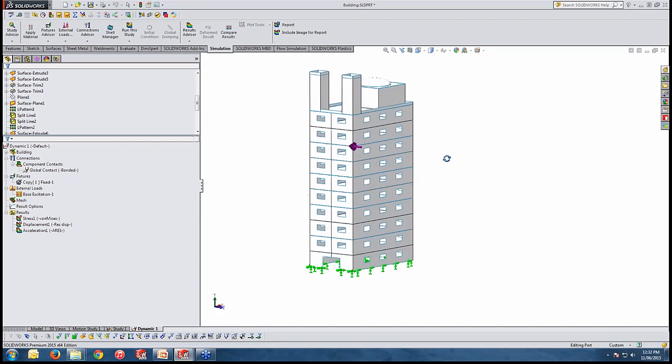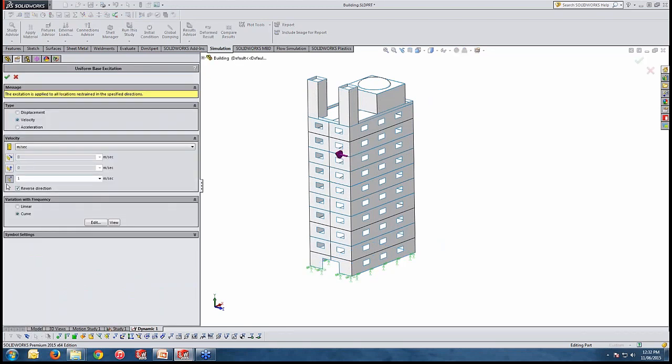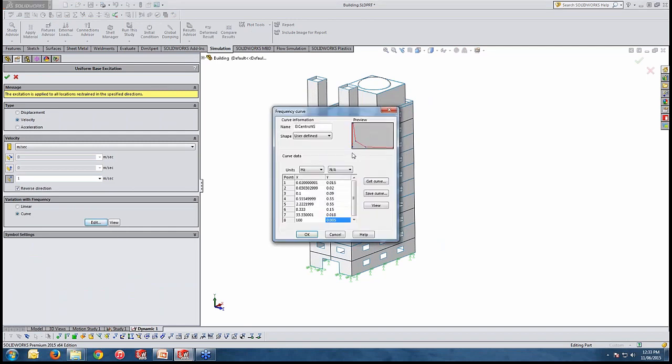The rest is what I've done is my base excitation. So simply I've put a northwest, north-south means along the z-axis, as 1 meter per second velocity. And the profile of this velocity variation as an earthquake entry, as you can see, is being here.